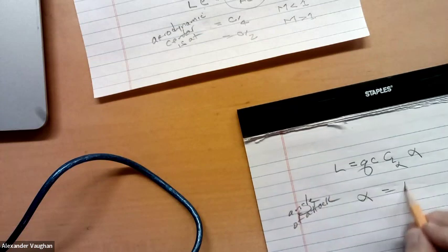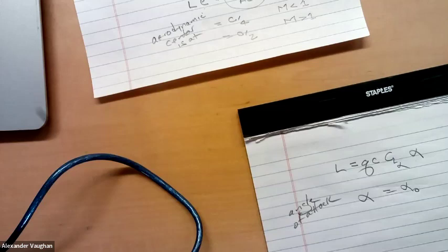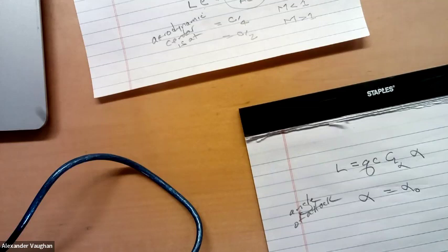And we think of it as being composed of two contributions. One is the initial angle of attack the airfoil might have when the spring is not deformed, when the spring is not twisted, plus an alpha sub E, which is the twist of the spring. So this is the twist of the spring.